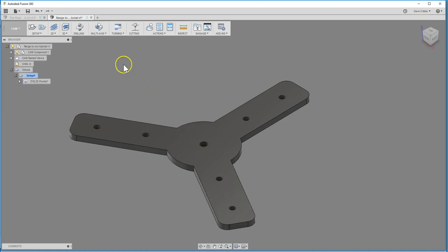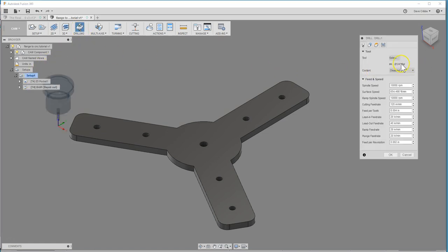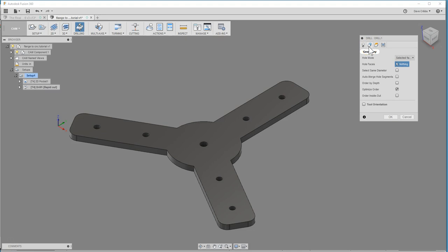The second toolpath we want to do is a drilling one. We're still here in the first setup. We're going to use the exact same bit. Leave the coolant disabled, 10,000 and 120. All those are fine. For geometry now, since it's drilling, we just can select those holes. The order that we select them in is the order that they will be drilled out. The CNC will just come in, plunge right into there,